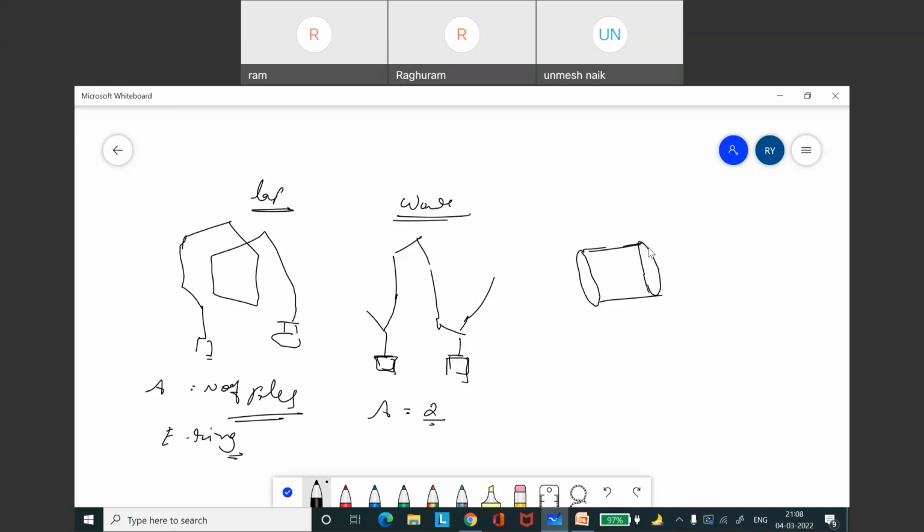At the end of this armature, they will place one more ring, which short circuits the armature windings. This is called an equalizer ring. Generally, in a lap winding, equalizer rings are required to make the winding mechanically better balanced. Whereas in a wave winding, equalizer rings are not required.